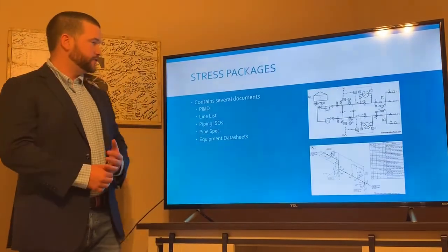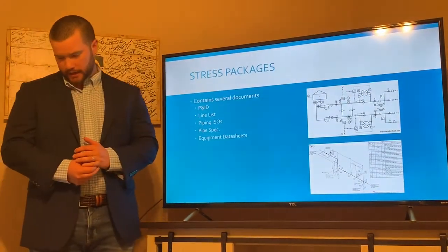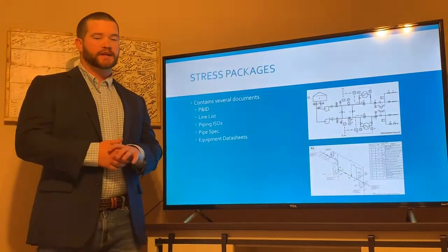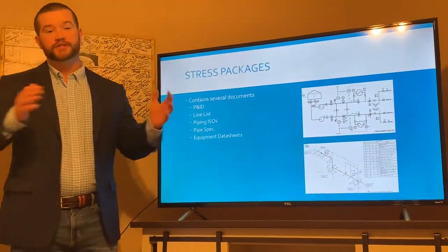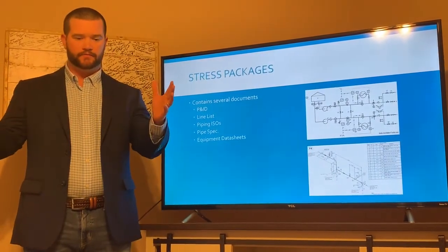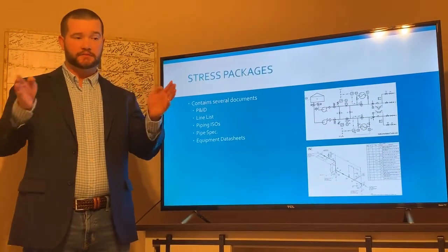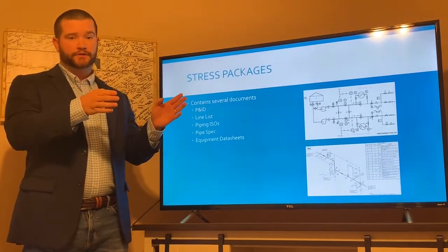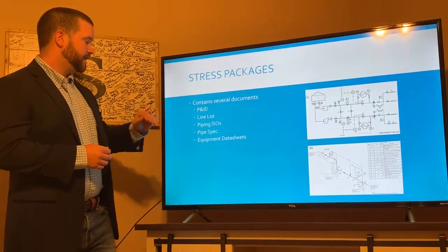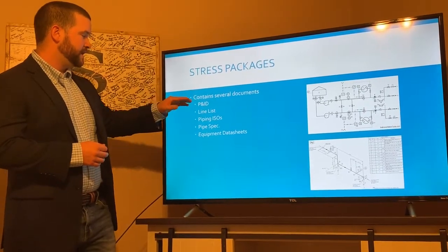Okay, so you're going to receive a stress package, and in that stress package, it's going to hopefully contain some reference documents pertaining to your stress system. And when I say stress system, that's just an area in a plant or refinery that needs to be analyzed for stress under ASME. So you're going to get a package, and it's going to have these documents in it. Hopefully, it's going to have a P&ID.